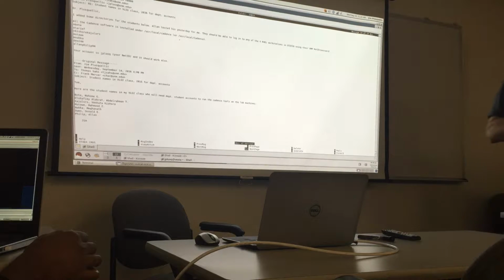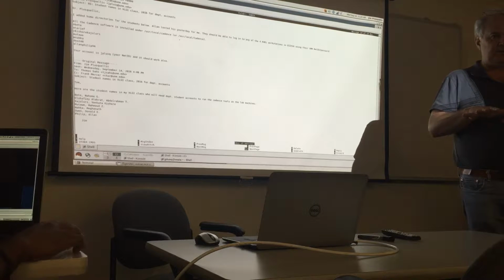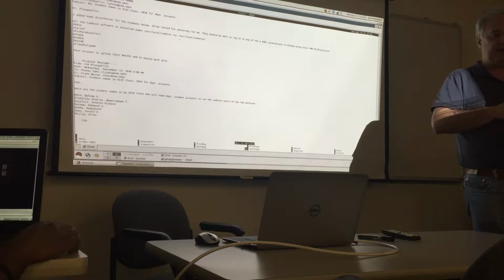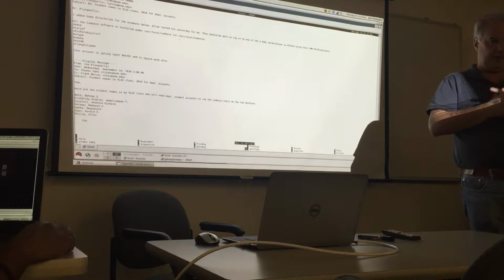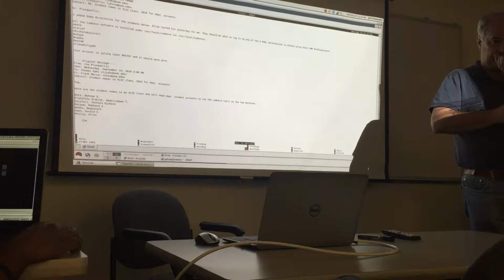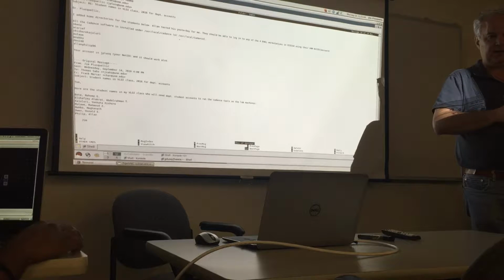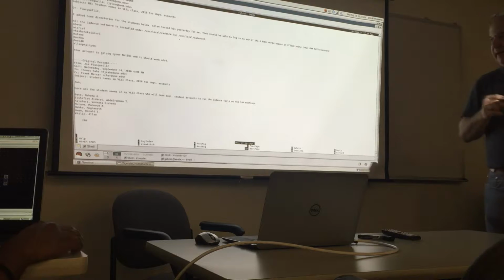The easiest way to deal with the inherited connection: all the library cells I gave you use them, so you'll have to continue to use them too. You can't just use VDD because the synthesis tool will have a fit. The easiest way is to copy the VDD and ground pin from layouts that I have into your layouts as you create them. This of course permeates. If you design something by hand with these cells, the parent will also have to be labeled with the inherited connection. So the format is...